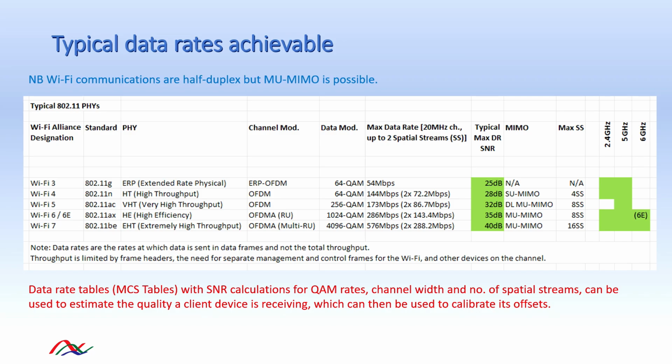If this is not the case, you might use two adjacent 20 MHz channels to form a 40 MHz channel and effectively double the rate on the channel seen here. Each rate here is also based on two spatial streams. Each spatial stream for a 20 MHz channel is sent at the 20 MHz base rate. Two spatial streams then double the base rate, and three spatial streams would treble the base rate, and so on.